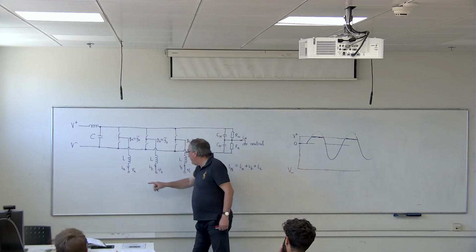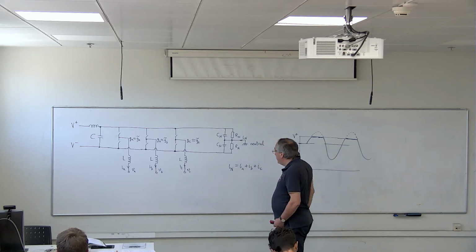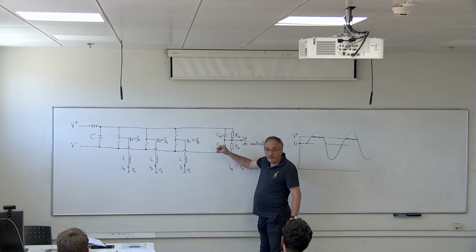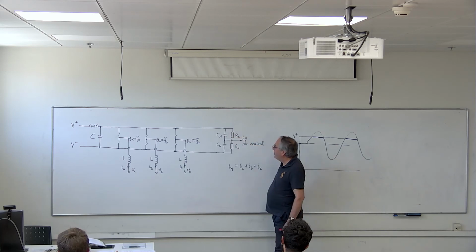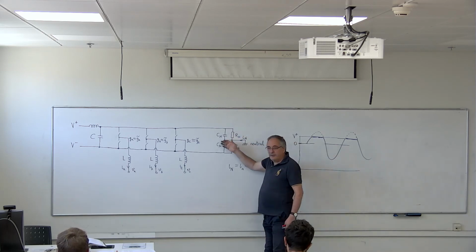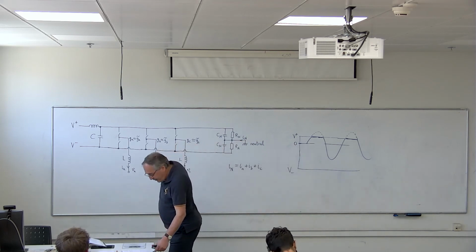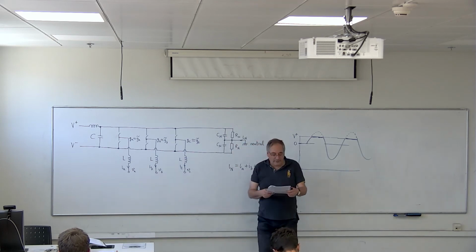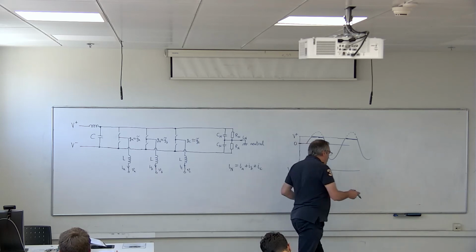So this will now come here, and you have a significant current that has to flow through the neutral line because it is this sum. That significant current corresponding to 2 kilowatt cannot flow through these resistors and capacitors because these are small capacitors and big resistors. It just cannot flow through. And so you have to provide a more complicated circuit, which is shown on page 8 of the lecture notes that you have. The more complicated circuit would be to add one more canonical switching cell.